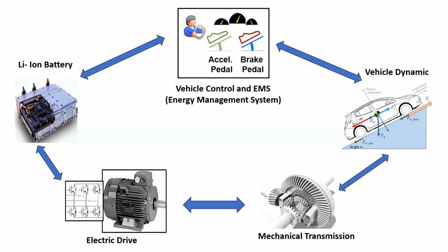But for this example, we are not going to use any components that are heavy weight-wise. What I mean is that if I have a Typhoon HIL simulator with a processing core inside it, and I use a heavy component, for example a 3-phase inverter or an induction motor, it will occupy some space in my processor. And that space determines the speed of the simulation. So if my model is very heavy or complicated, it will probably take some time to run. But today we are going to design a model that will run completely on signal processing components.